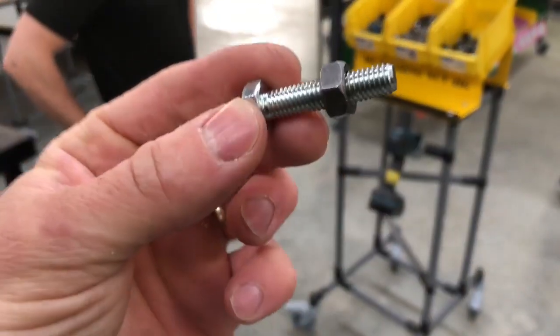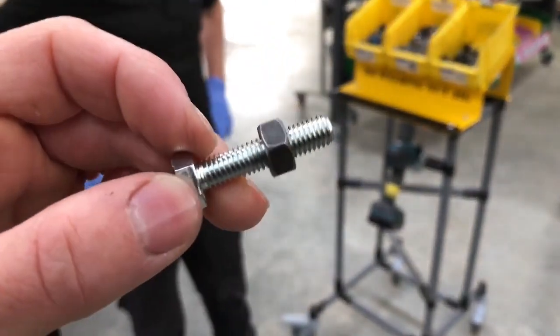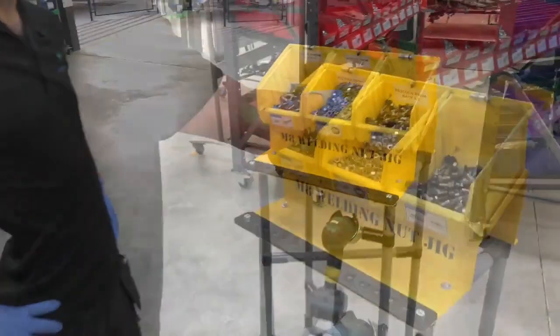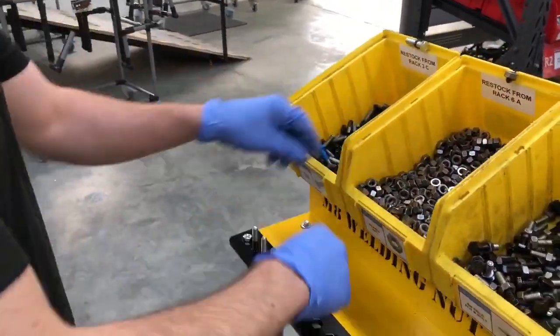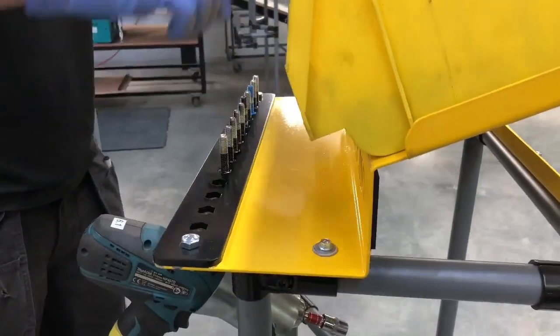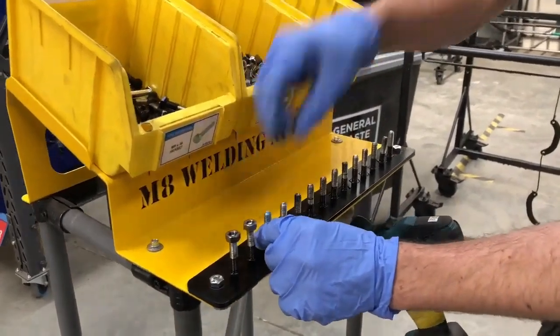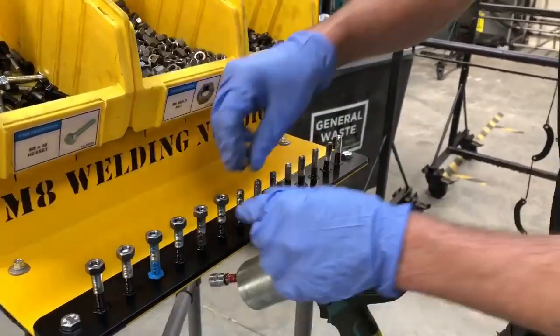The goal is to put the nut on the bolt at the correct level. So let's see how the after video has improved this process. The first step now is to lift the bolt and set it into the located hole on the metal plate, which holds the bolt in place. The next step is to put the nut on the bolts, and both hands are now free to carry out the task.